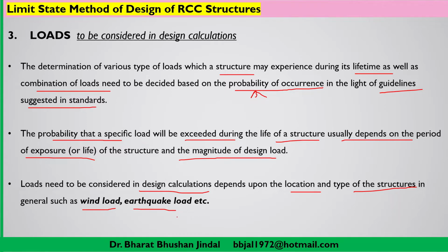Whether earthquake load is to be considered depends on the geographical region of the area where you are going to be constructing the building or any structure which you are going to design. So what load you have to take into consideration depends on various factors. That means what is the type of the structure. Suppose there is a tower type of structure, having a greater height, then definitely wind load may be affecting it. But if you are just going to construct a residential building, maybe single story, double story, you may ignore the wind load criteria depending upon the location also.